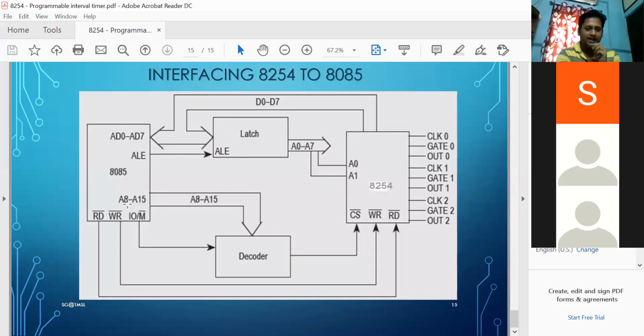Now the other address lines, A8 to A15, along with this IO/M bar, go into a decoder circuit so that a chip select signal can be generated, and it enables this IC. After enabling this IC, you can perform the read operation or write operation using these two control signals, read and write.